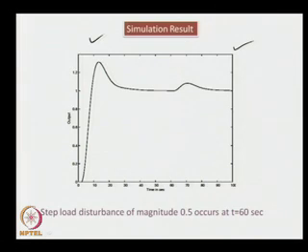If we carefully look at the response, we have got a time response which is giving about 25% overshoot and a settling time of about 30 seconds, and we have got a disturbance rejection also. It ultimately settles down. If I draw the reference line correctly, it goes in that form.